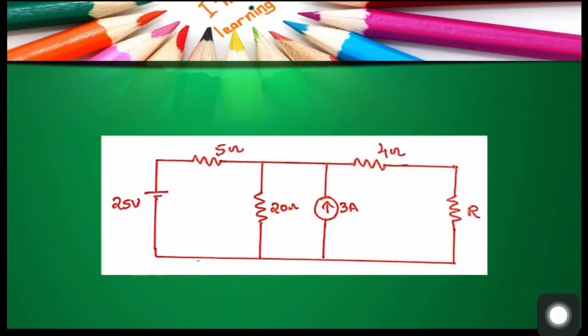So what we are going to do next is find out the Thevenin equivalent resistance of this source network. Do you remember what is Thevenin equivalent resistance of a network and how to calculate its value? In fact, Thevenin equivalent resistance is nothing but the internal resistance of the source network looking through the open circuited load terminals. For finding out its value, we are supposed to set all sources present in the network to 0 and calculate the internal resistance looking through the open circuited load terminals.